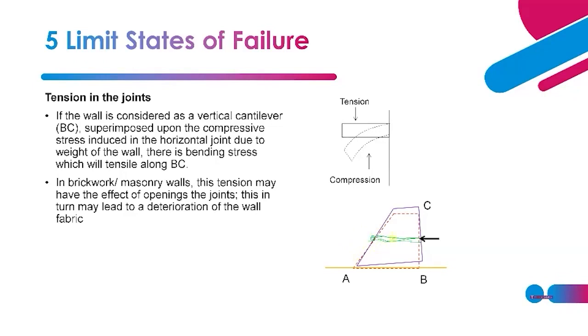To avoid water seepage so that water will go down. The problem is, it goes down. So below this there is a drain, usually like that. Sorry, the retaining wall will easily deteriorate because of other forces. This one is acting on the retaining wall, and then you have openings with joints. Your masonry wall is also joined using mortar and so on. So it will lead to deterioration of the wall fabric.